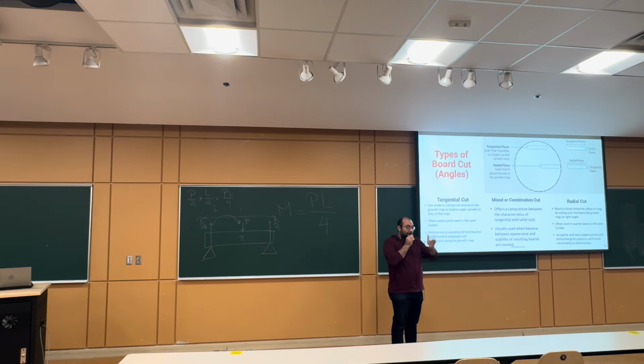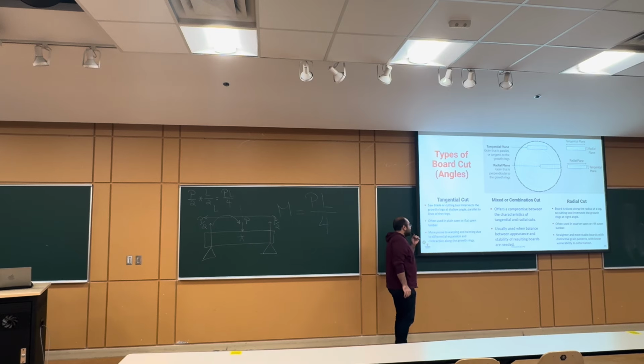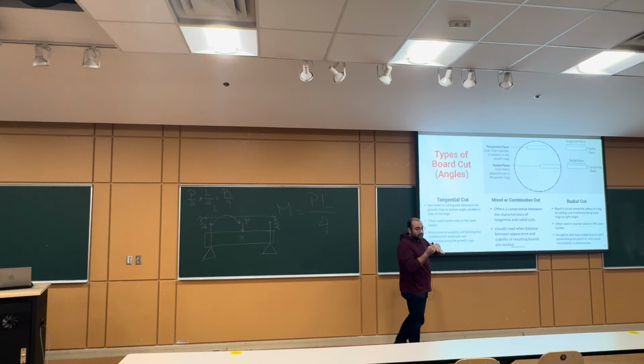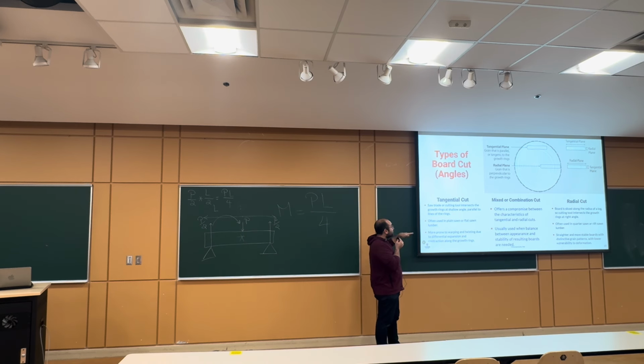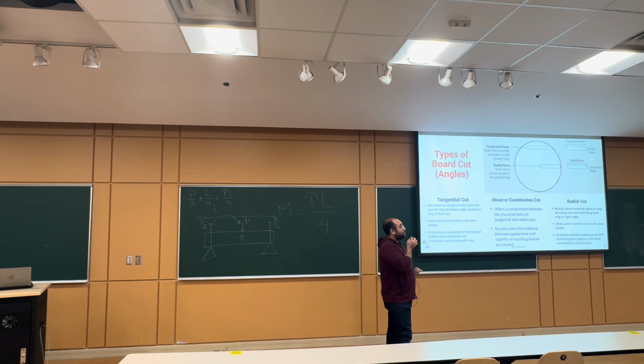So we are cutting parallel to the line of the rings to have those slices that we have seen in the past slide. This is often used in plain sawn or flat sawn lumber, and is more prone, as we said, to warping due to the difference in the properties between the different planes, and twisting due to differential expansion, uneven shrinkage of the material and contraction along the growth rings. So this product is accompanied with the plain sawing technique, and those are its properties.